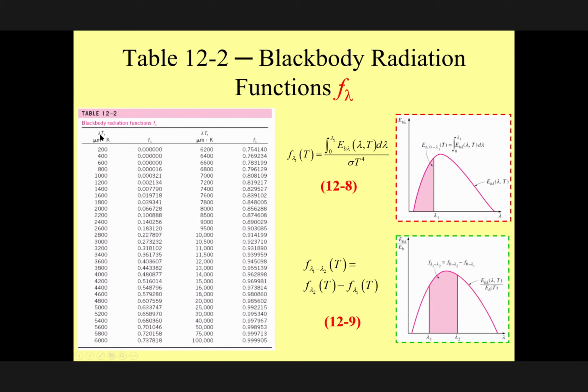I calculate lambda 1 and T, and lambda 2 and T, and subtract them, and this portion of energy is between wavelength of lambda 1 and lambda 2. As I mentioned, this is very important for us sometimes because we are designing different materials, and we would like to make sure this characteristic of that material is somehow that captures the maximum amount of energy that we have.